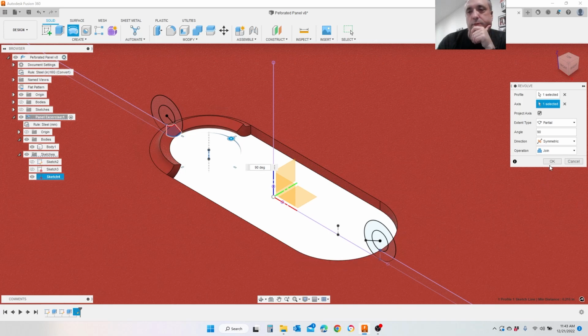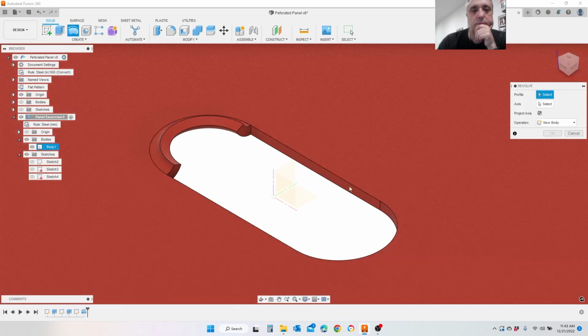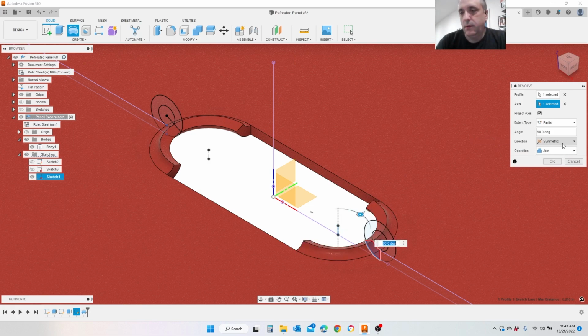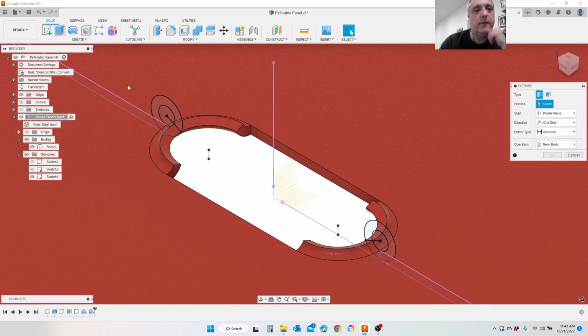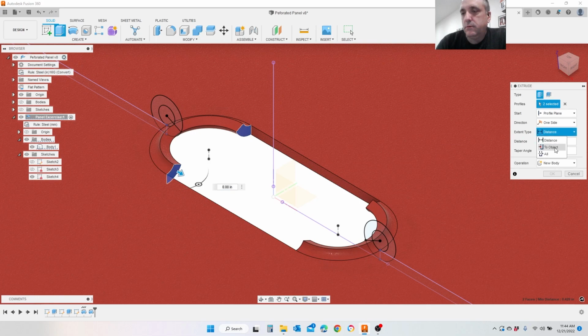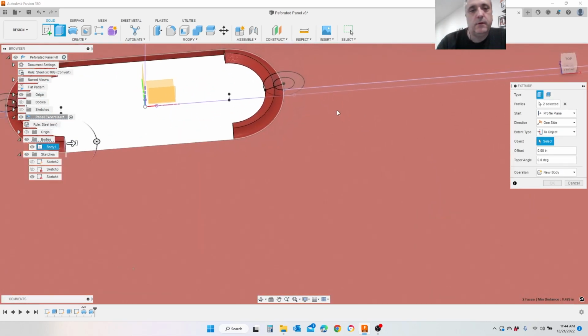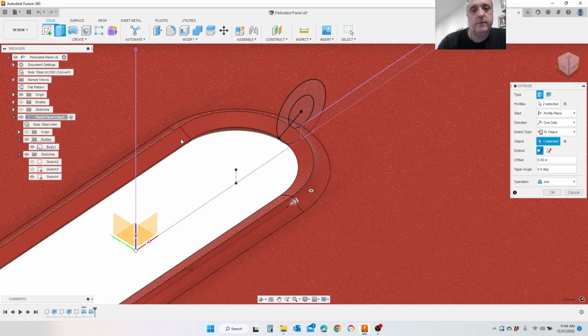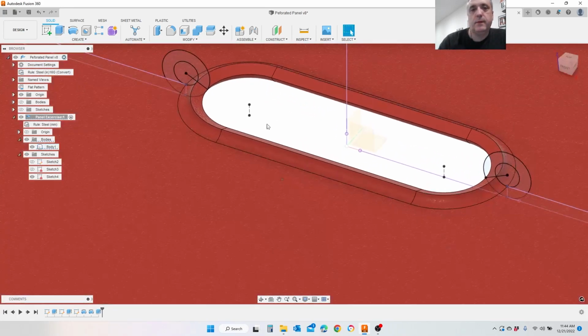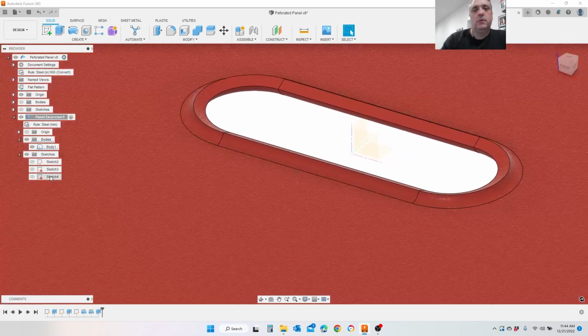And then we're going to do the same thing over here. Repeat that. Turn drawing back on. It remembered the settings, same thing. And then we're going to do an extrusion from the ends of these to object, to this face. And you can see in all of this as I'm doing these, I'm joining these on this body. Turn off our sketch. Well, actually, let's leave it there.